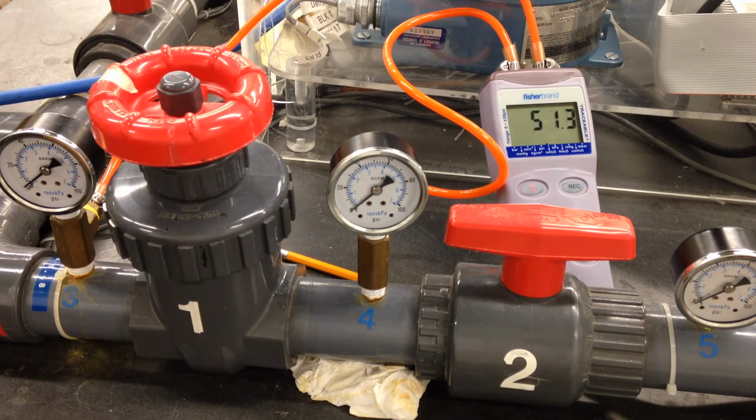As you can see, the beauty of a digital manometer is you have a number of options. With the conventional manometers that we used in the other part of the experiment, we didn't have many options. We just had to measure inches of water or whatever it's graduated in, and that's it. We can do PSI and inches of mercury, which I try to avoid because the stuff's poisonous. And as you see, as I increase the flow, the head will go up, which according to the theory, if K is constant, then the head drop will vary with the square of the velocity going in. And as you can see, we can get considerable head loss at just a quarter opening.